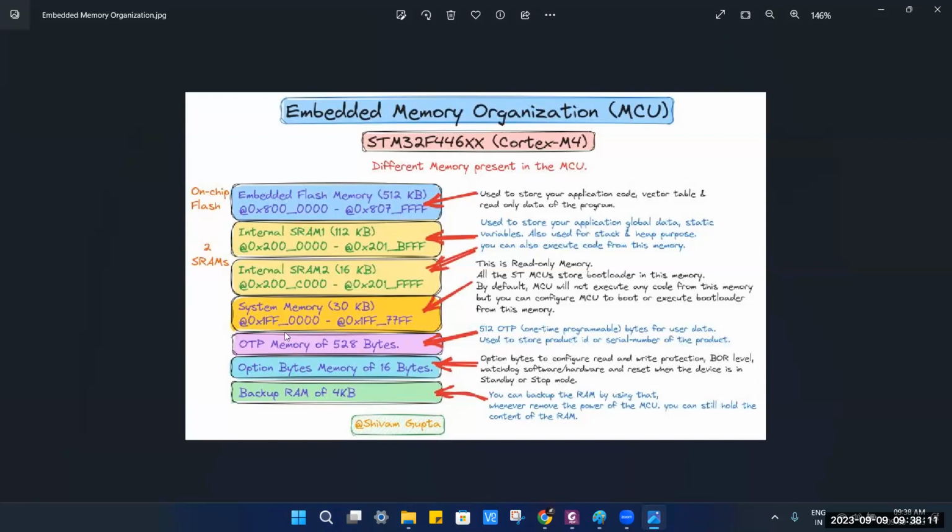Correct. That is for the firmware scenario. Actually, this OTP memory is flashed before production itself. Let us suppose I have a router, so I will put the OTP memory before production. The user cannot read or do anything to it, because after putting this, we will set it as read only and write protection. Getting my point? Yes, yes.